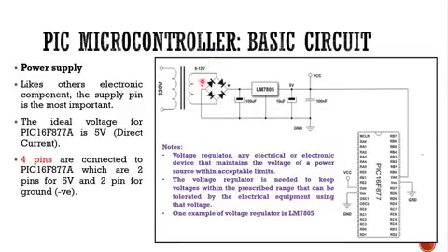Then the AC signal is converted through this full bridge rectifier; the value is still 6 to 12 volt, but it is now a DC voltage. Then we go to this capacitor, which smooths out the output from the full bridge rectifier, still around 12 volt DC.